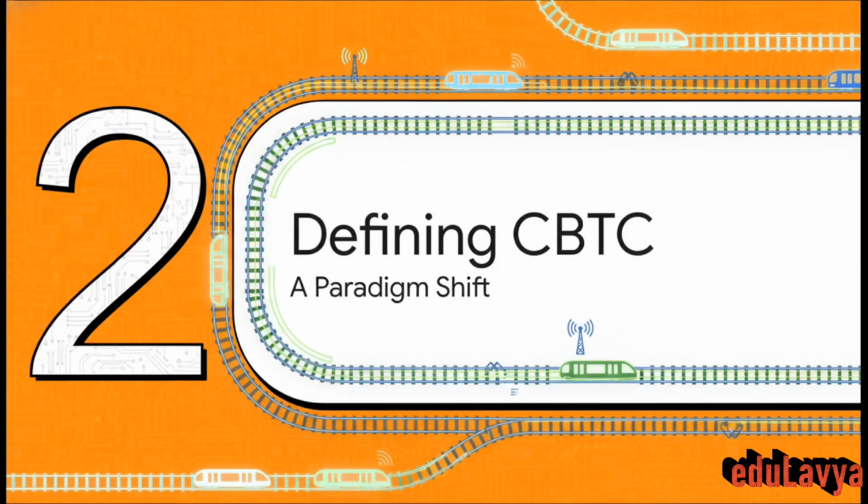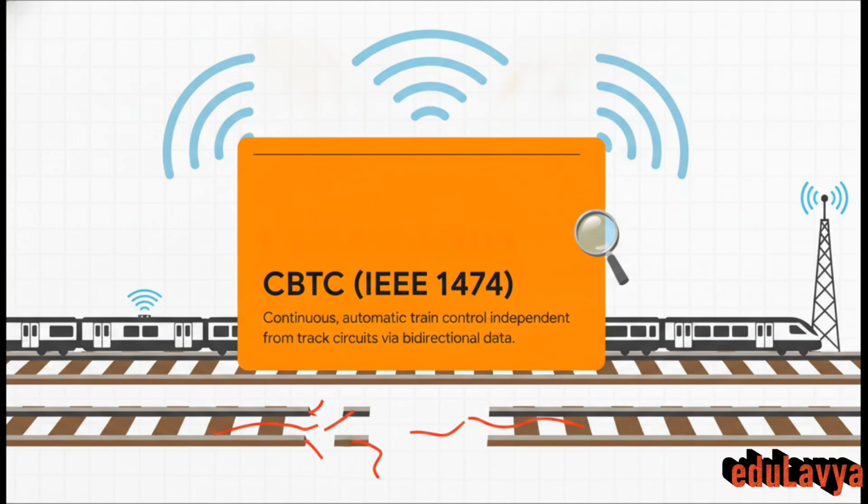Moving on to Section 2, defining CBTC. Let's look at the technological paradigm shift that was required to actually fit more trains onto that exact same track. And that brings us to the formal definition of communications-based train control, or as the IEEE 1474 standard puts it, it's a continuous automatic train control system utilizing high-resolution train location determination that is completely independent from physical track circuits. Instead, it relies on continuous, high-capacity, bidirectional data communications between the train and the wayside equipment.